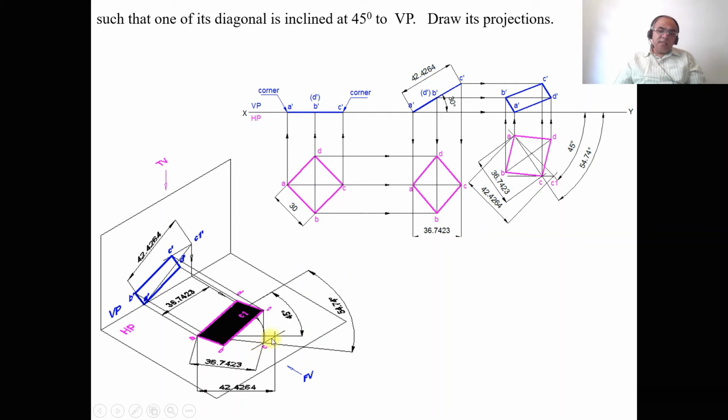So we have rotated so that on this locus, this is the one where you are going to get this apparent length, and then on this diagonal you keep this square, and then write the corresponding front view. So this front view which you get here and also what you get here, both are one and the same. As we keep rotating the second position top view, you can see here that the point which was C1 dash has moved to C dash here. So this is how you will be able to understand this concept in 3 dimensions.